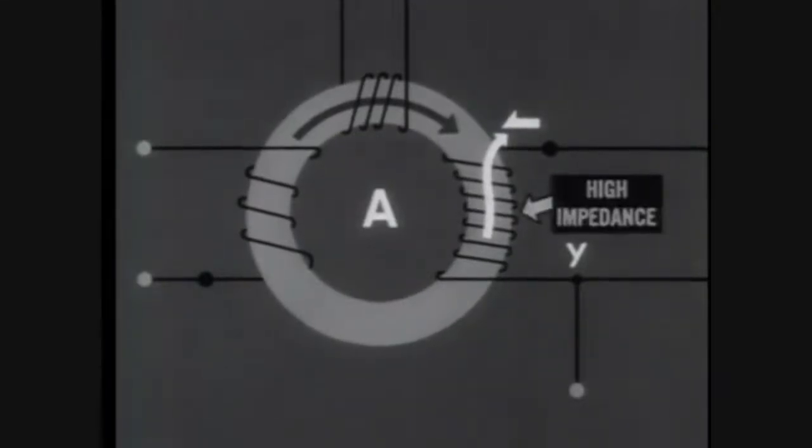But as one result of the complete change of flux, a large counter EMF is induced in the winding. The impedance now presented by the output winding is high. In fact, since this winding has more turns in it than any of the others, the impedance here is the highest in the loop. Its effect on the upper branch current is to make it smaller throughout its course.